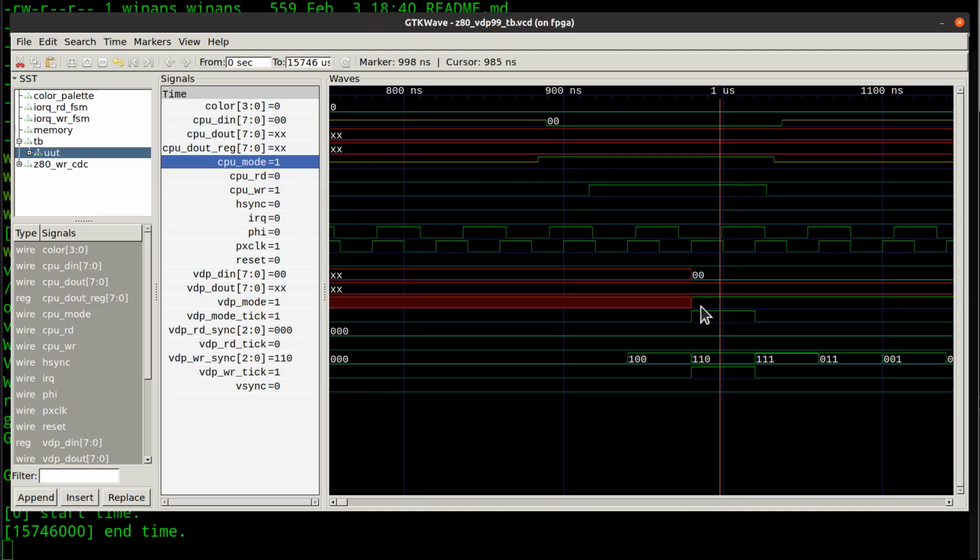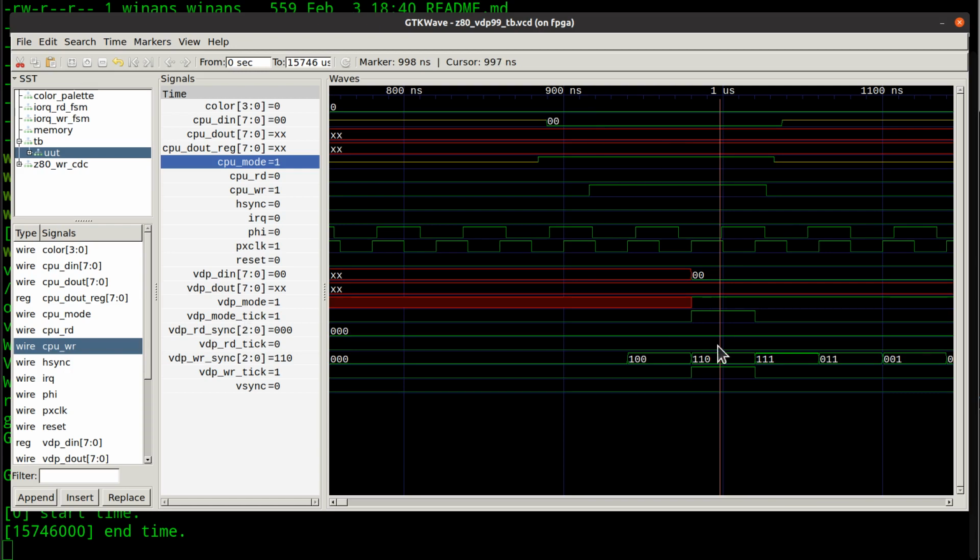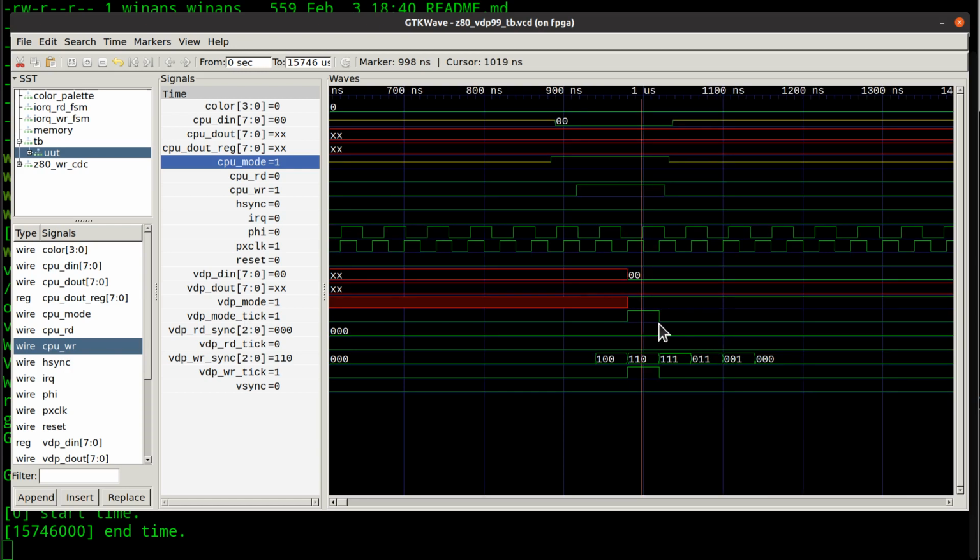So what we're looking at, right now we don't care why the CPU and why this test bench is talking to these registers. We just care that it is, and we want to look and see what's going on with the synchronizer here, this shift register, and the timing relationship in here to make sure that when we're all done, we have the data we need when we need it, okay?